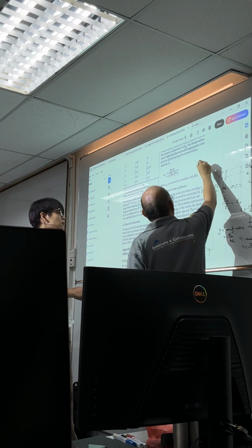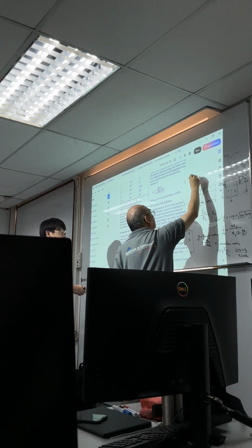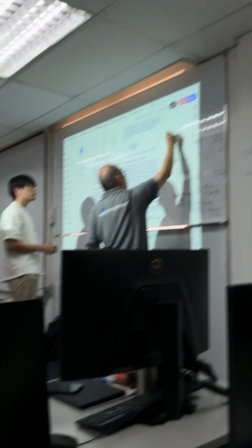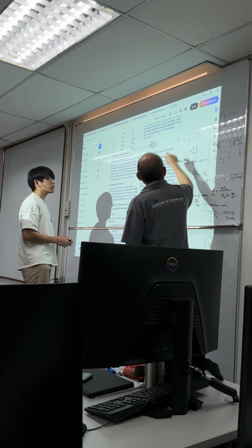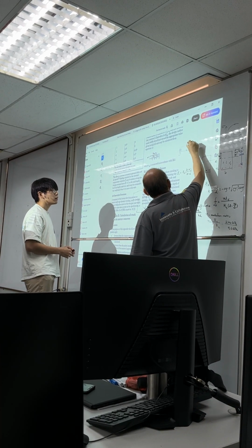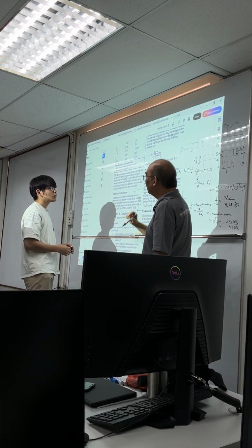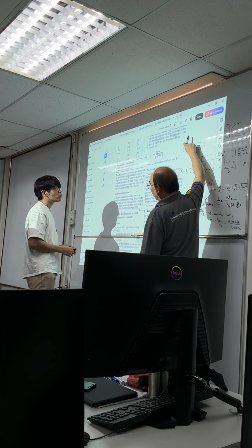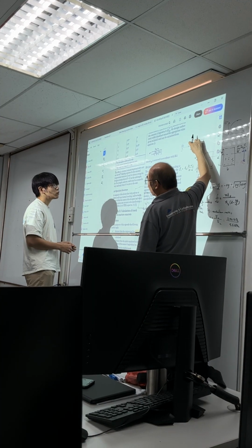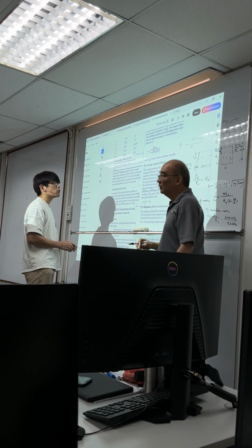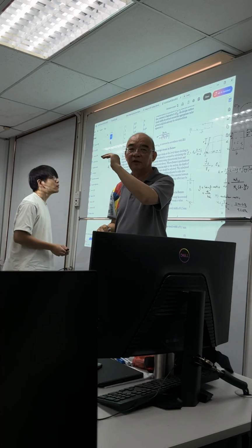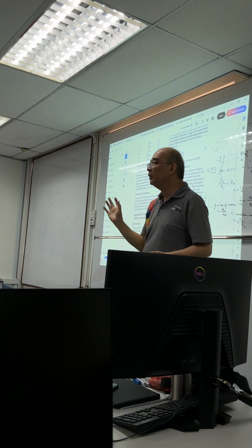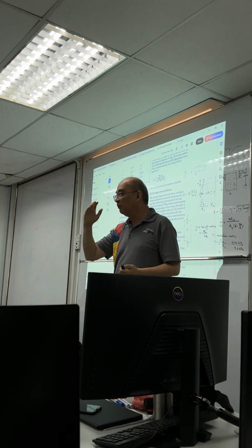Let's say your member is here, like this. When you apply loading, there will be crack here and there will be crack here. Your crack here is because your moment is like this, and this is in tension. So this is actually a tension crack. This section is a compression face. This section is the compression face. The top is not always a compression face. Okay? So you need to differentiate between the top and the compression face.